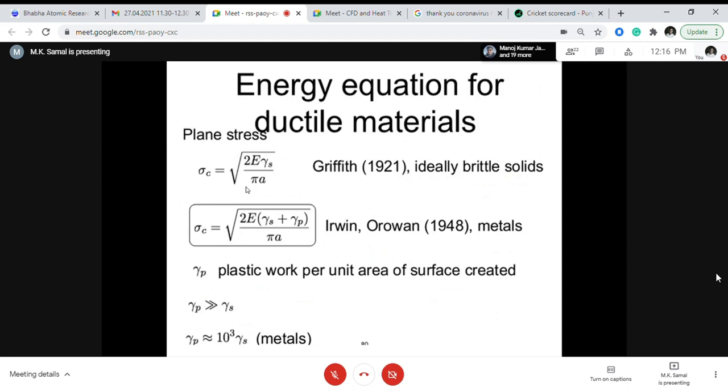If you use a thin specimen for the test, then you get a higher value, so your design will be unconservative. To be conservative, plane strain conditions are always ensured in the experiment. So we will be talking about the plane strain fracture toughness in all our fracture mechanics lectures. To summarize, the critical stress or fracture stress is the remotely applied stress.